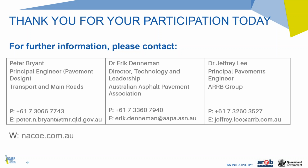Actually, that's a very good question, and we're not looking for identical specimens, because what we're looking for is the normal or natural variation in the asphalt properties that you would encounter with a mix. Fatigue testing has an inherent massive scatter, and that's why we need 27 beams to have the level of confidence around the results. That's why you need so many samples, and the aim is definitely not to create 27 identical beams. There's a certain air void content distribution that we're looking for, and that is perfectly allowable within the test method. And actually there's some space for contractors to be smart about how they produce their specimens as well.